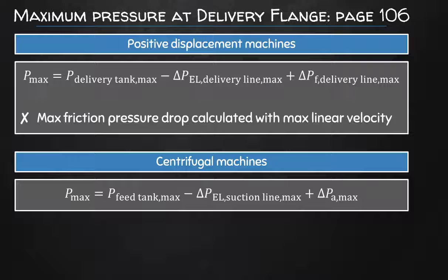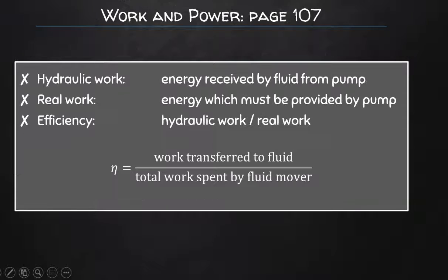Well, what would happen is the pressure would simply build up more and more until mechanical failure is reached, because the volume of fluid that you are now pushing into the pipe has nowhere else to go but remain inside the pipe, and on top of that you add more and more volume, and as you increase the volume you increase the density of the fluid, and eventually this would likely result in a burst pipe wall, which is obviously going to be detrimental to the process, and you can harm your fellow colleagues if this is done.